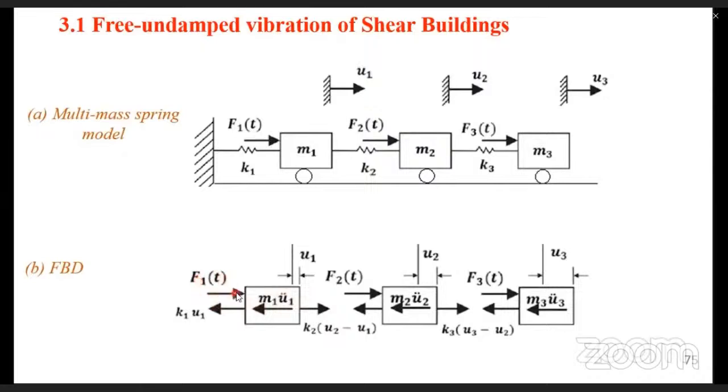So you have force 1, you apply this applied force. We have the stiffness due to column 2. Now it acts in the direction of the applied force. The same case that you have done in the previous slide. But now we have the restoring force due to inertia and the stiffness of column 1. And same case you can do for the second floor level mass. For the second floor level mass, we have the stiffness contribution because of K2 and K3. And same case for M3.